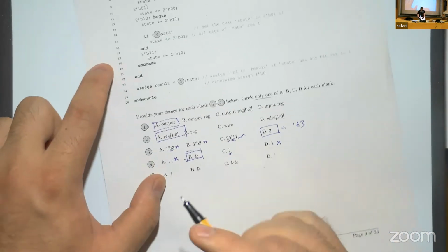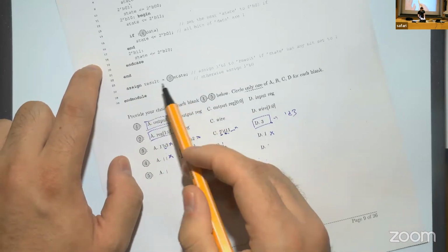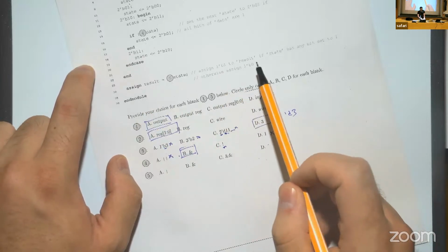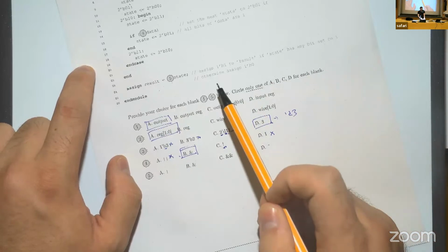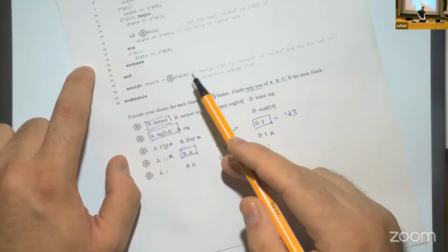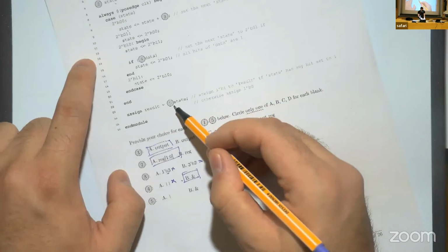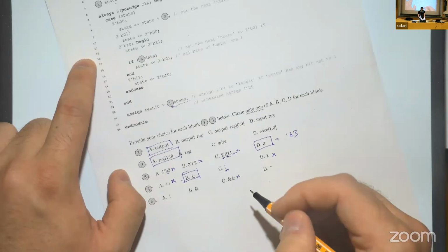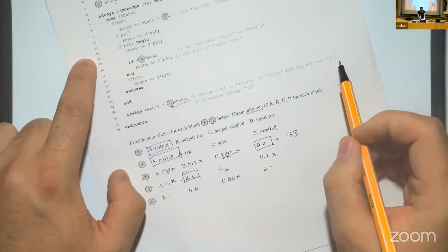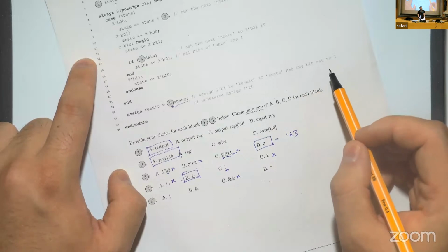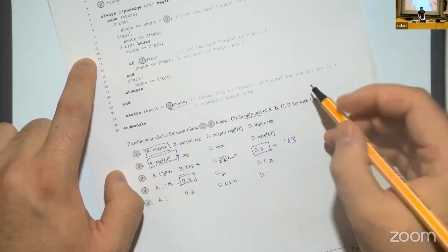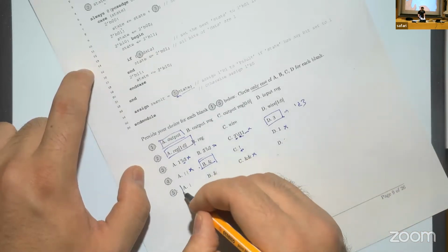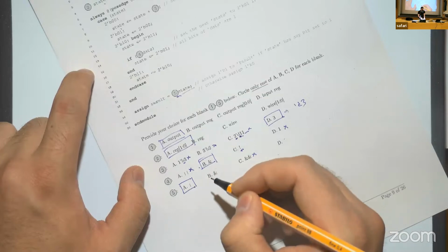The last one is the fifth. It's, again, line 24. It says assign 1 to result if the state has any bit set to 1, otherwise assign bit 0. We know that it's a similar situation, right? It's at the beginning of the variable, so we cannot use C over there. It also says that it has any bit set to 1. So if any of the input is 1, the result is 1. We can easily say that it's OR reduction, which makes it A.